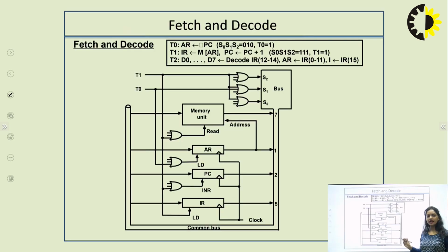This is the hardware diagram showing where we are getting that instruction, who will first initiate that instruction address, how that will be decoded, where it will be going and where it will be executed. So here we have a multiplexer which will perform a selection operation among these devices. This is a common system bus diagram, but this is a half diagram of that common bus system because we need only these 4 units for its functionality. So first is your memory unit. This is your RAM memory.